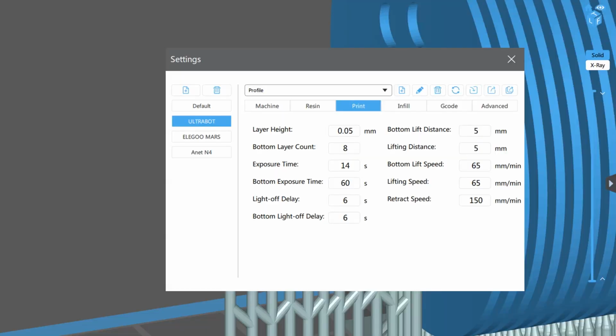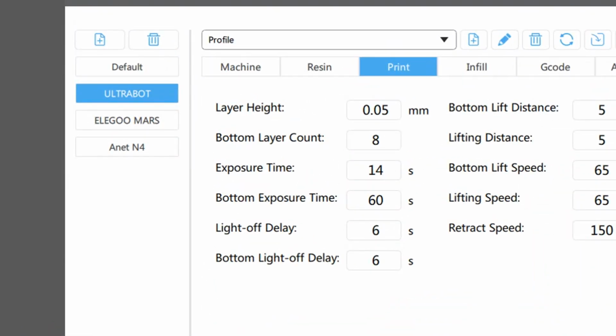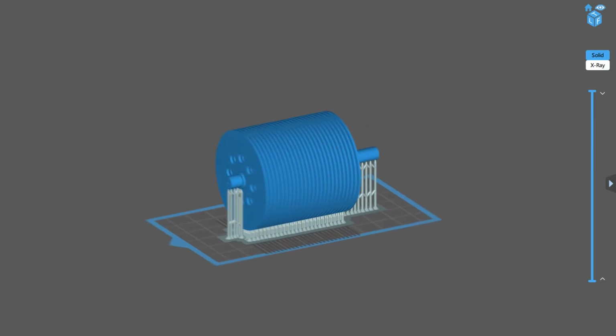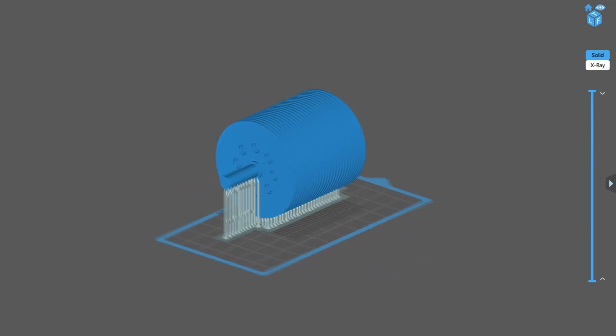But after a while I tuned my process. Beginning at the slicer, it's important to use the recommended curing times. It's also important to orient the parts properly and avoid supports in areas where you need dimensional precision. Like, for example, the axis of the turbine that needs to fit the ball bearings perfectly to avoid vibration.